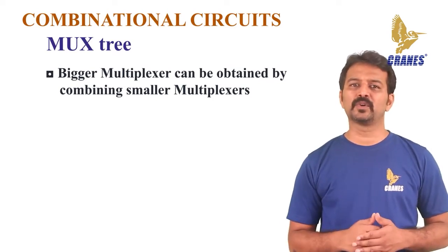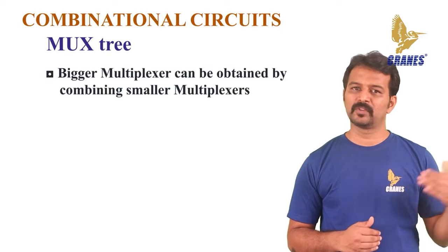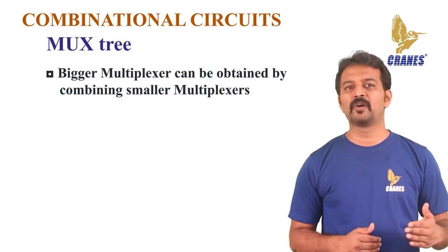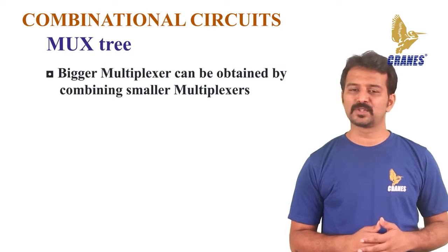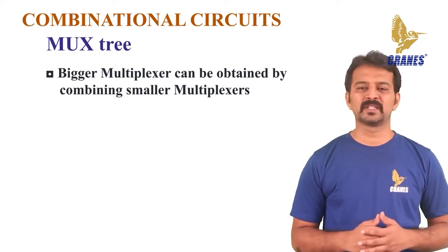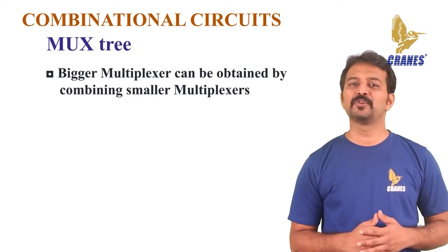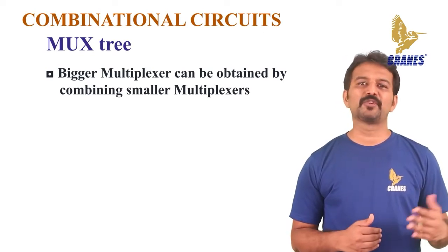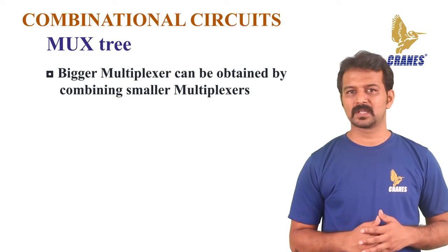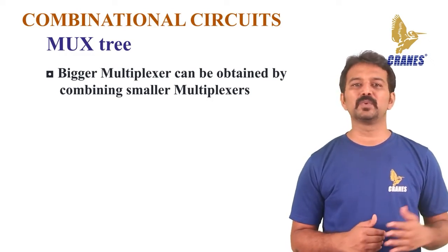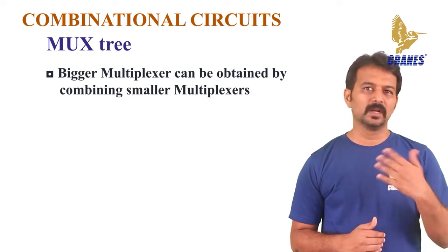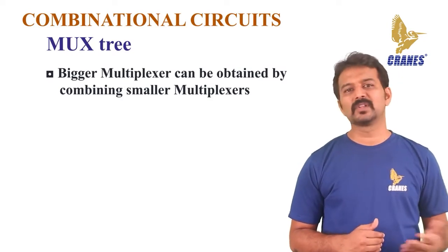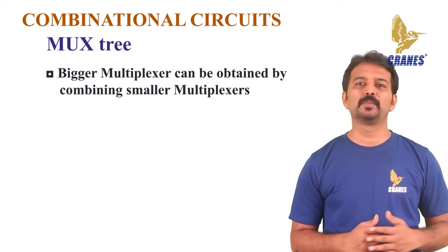It is also common to combine lower order multiplexers like 2:1 and 4:1 mux to form higher order mux like 8:1 mux. Now for an example, let us try to implement a 4:1 mux using a 2:1 mux. To construct a 4:1 mux using 2:1 mux, we will have to combine 3 2:1 mux together. The end result should give us 4 input pins, 2 control or select pins and 1 output pin.